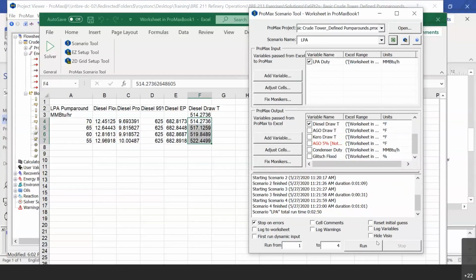All right. So the question is now, could you just use the actual number of stages? Well, do you mean actual number of trays? Okay, good. I would use actual number of stages. That's going to be your best tack for these models. So once I've made the sizing based on ideal stages, we need to simulate the heat and mass transfer model considering real trays. Typically, from a design standpoint in my EPC experience as well as here, I've seen crude units modeled utilizing equilibrium stage modeling and not the heat and mass transfer model.